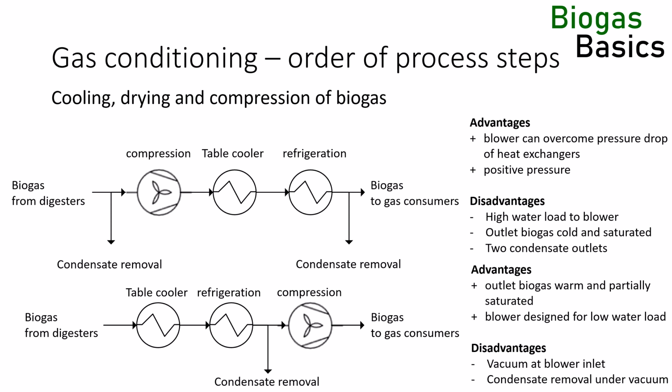Blowers are also often undersized because of unexpected high pressure drops in biogas pipes, or because the water vapor load is forgotten in the design phase. Chillers are another critical point in the gas conditioning unit, as they fail frequently and benefit from a duty standby arrangement.